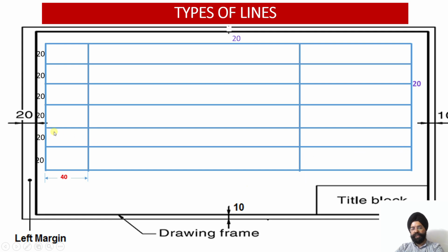So this width of the column is 40 mm from this end, and this width of the column is 150 mm measured from this end. And for the 100 mm line I have to draw, I leave 25 mm from either side. So these are two construction lines which I am going to draw. You can see construction lines will be lighter ones, whereas outlines will be darker ones, using an HB pencil. So the basic framework we have designed.